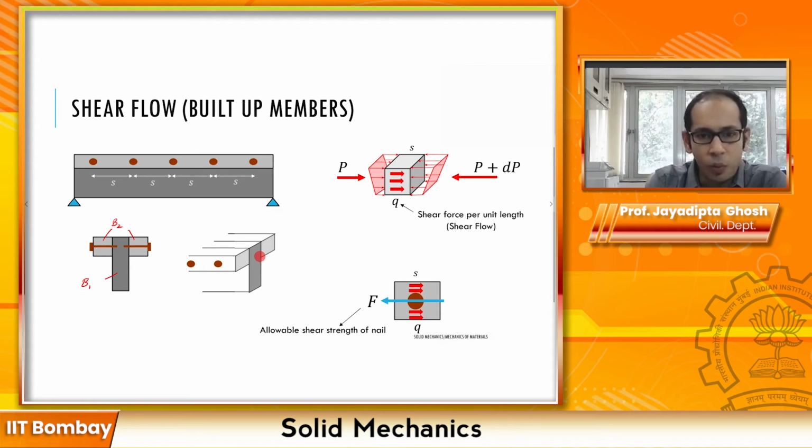So what will happen here, if you have these kinds of triangular stress distributions, which are the results of the moments that you have, part of that over there. As a result of that, this board will try to be pushed in this particular direction if you have the shear, because your longitudinal shear is complementary to the transverse shear that you have. And essentially what these bolts are doing is keeping everything intact, keeping everything in place. So you have two rows of bolts over here.